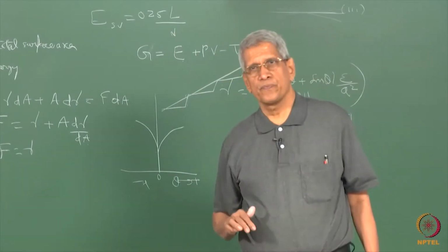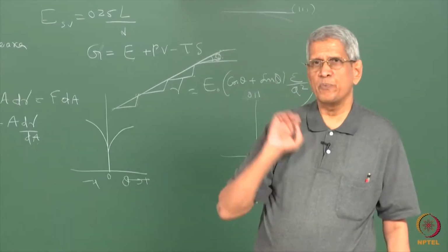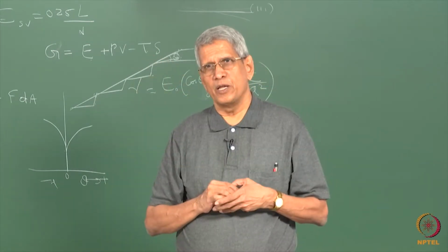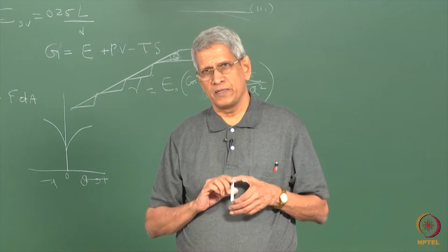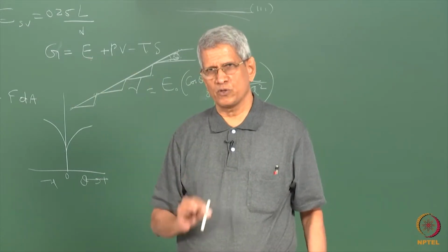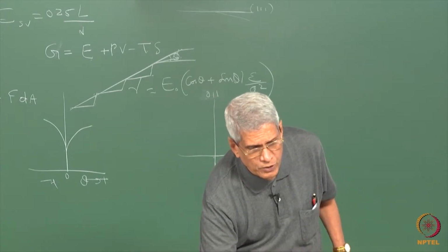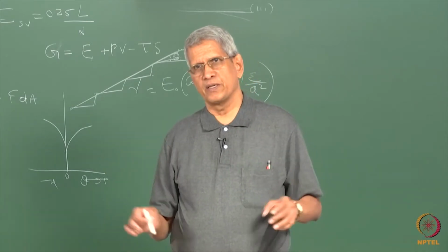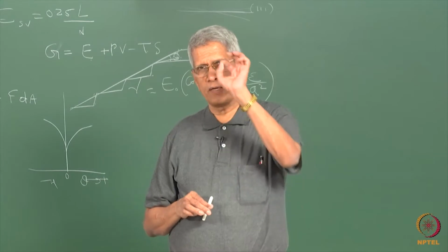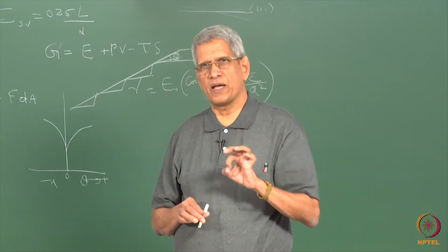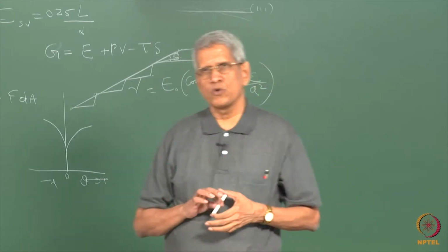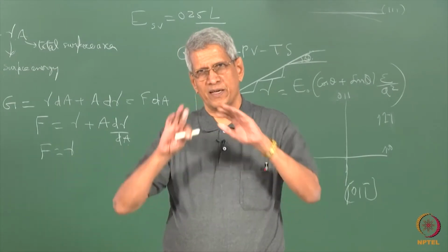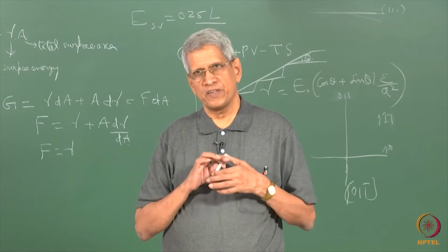Suppose we assume that a crystal is being grown from the melt. Depending upon the surface energy which is available, that is going to control the rate at which the surface will grow. With respect to that, we get some faceted surface, right. The faceted surface can always occur. Suppose we take a rod of a material, or a ball of a sample, take it very close to the melting point and keep it for a long time. The atoms should rearrange on the surface and it should take a faceted shape.